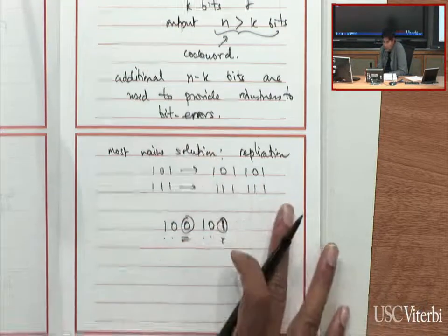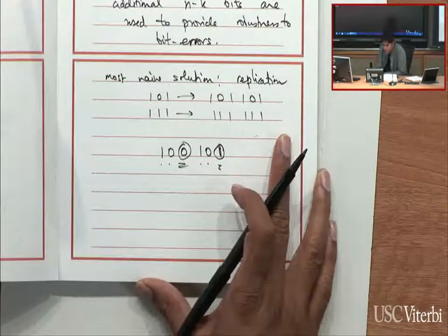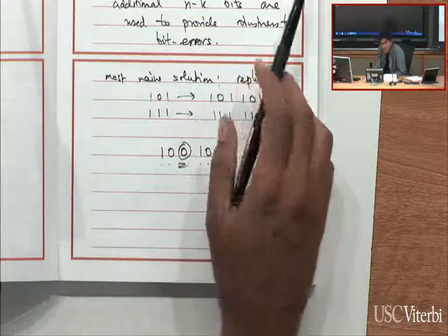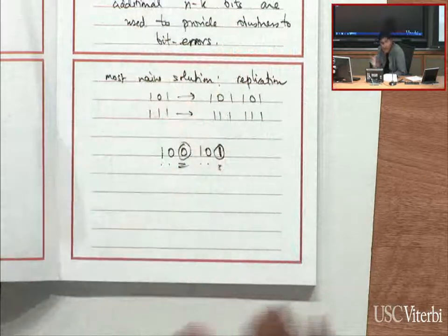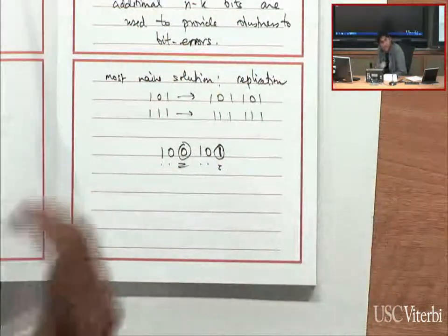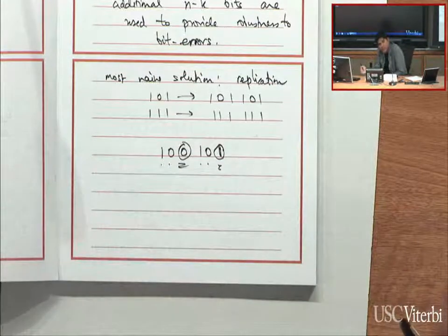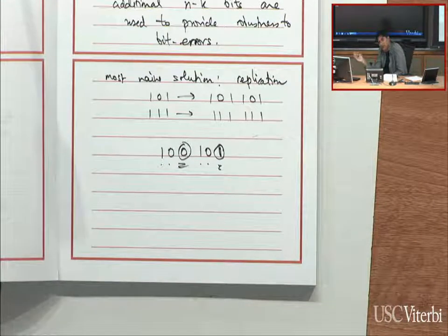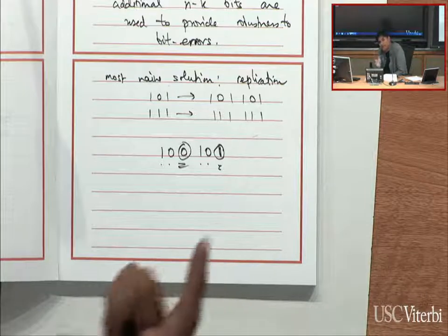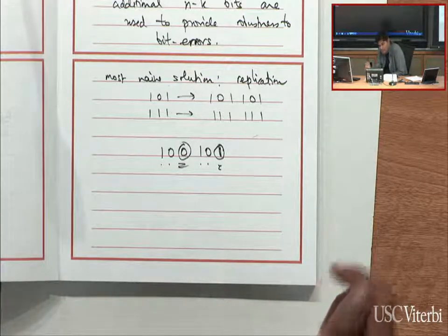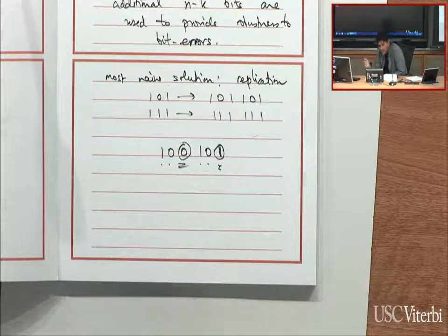So block codes are, think of them as very carefully designed transformations. There are linear block codes, which are just linear operations you perform on the input bits to generate the output code words, and then a corresponding decoding operation that comes back from the received code word to the original bits that tries to minimize the probability that your decoded values are in error.